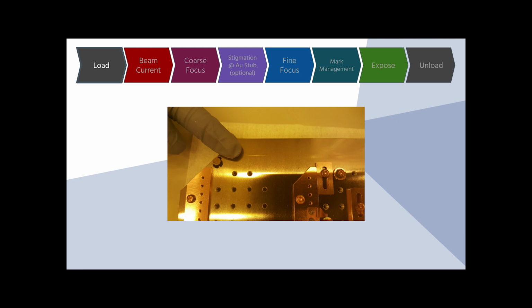We have also had multiple instances of folks closing the load lock gate valve with the pallet not fully retracted. In the image on screen, you can see me pointing at the scar that was left in the pallet after one such misadventure. Take care when loading and unloading the sample pallets to be sure that the stage is in the correct position and the pallet is clear of the gate valve before opening or closing that valve.